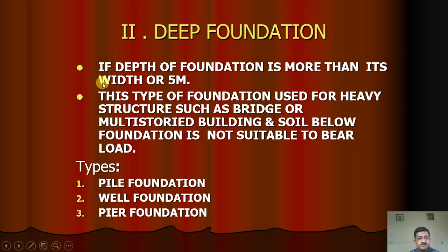Deep foundations: if the depth of the foundation is more than its width or 5 meters, it is called a deep foundation. This type of foundation is used for heavy structures such as bridges or multi-storied buildings, and where the soil below the foundation is not suitable to bear the load.